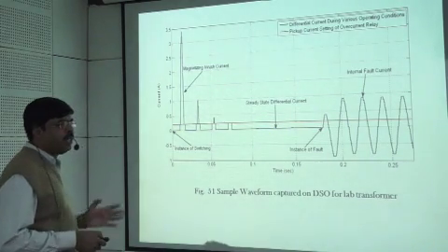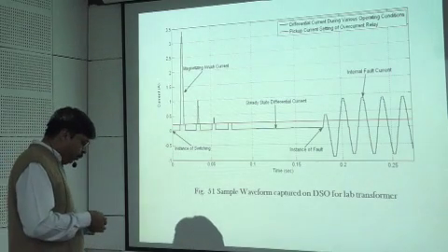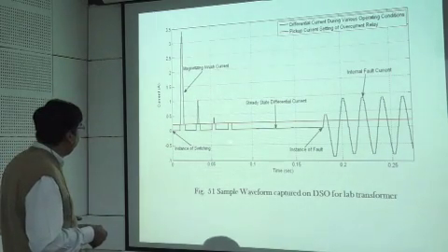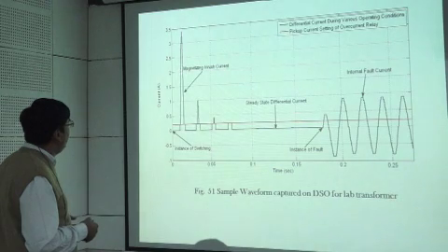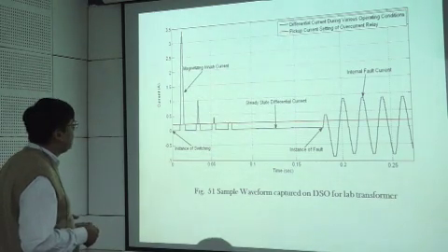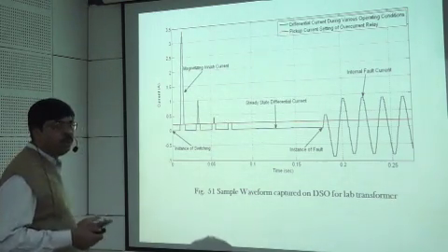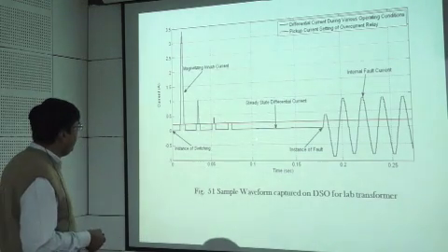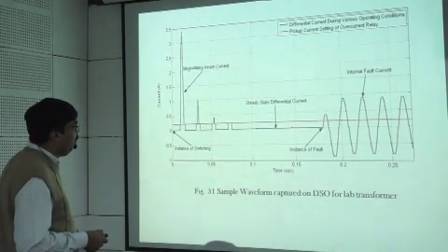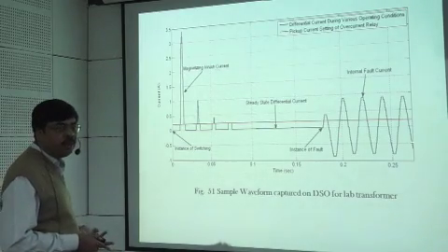Here I have taken a fixed threshold condition. For the first 3 cycles, the operating is more than the pickup, but this is not a fault. The algorithm should not give a trip signal. Here it is less. And here, as soon as we have a fault, it should be diagnosed as a fault.